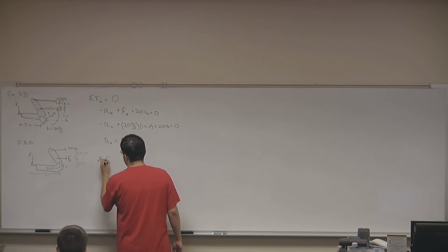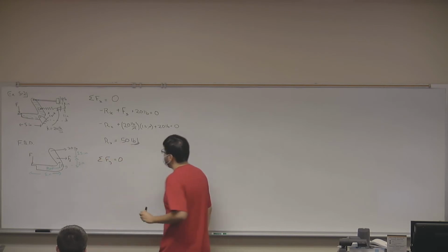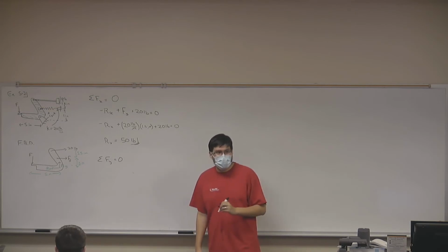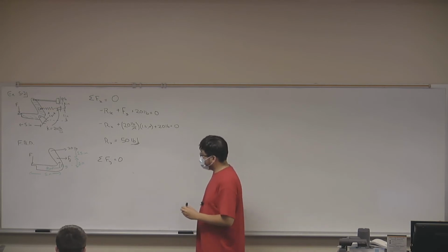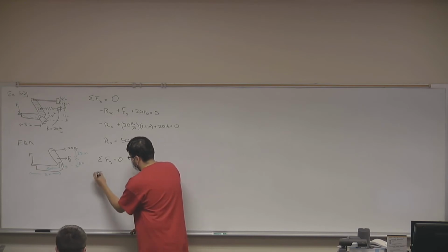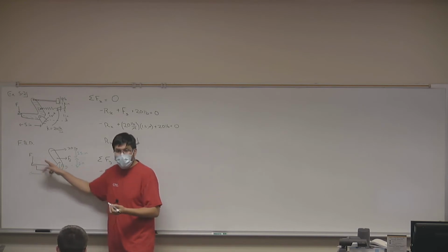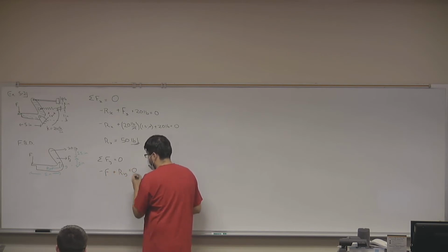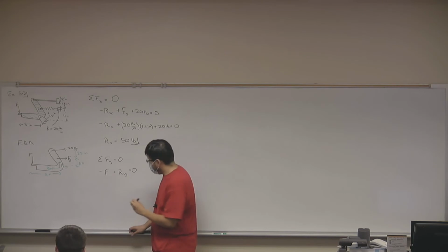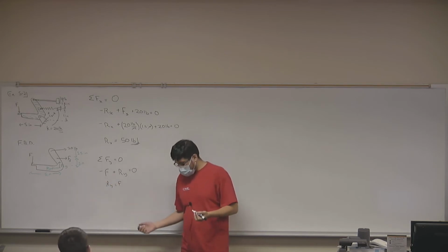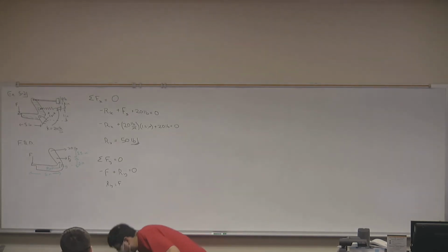So I get sum of forces in the Y direction equals 0. Luis, again, what forces can you identify in the Y direction? The force of the hinge, the reaction. Okay, good. We have the force that we're looking for. That's our unknown. We have a reaction force equals F. Uh-oh. We have a problem here. We get that our reaction force equals our force, but we don't really know what each of them are. So this equation is not very helpful for now.